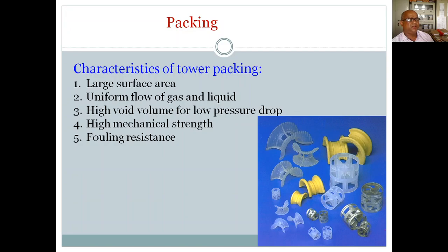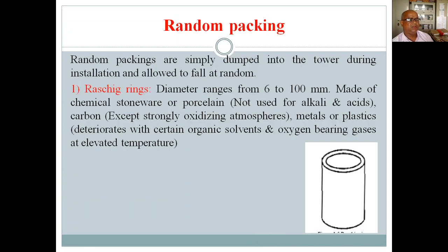So the characteristics of packing tower packing: larger surface area, and uniform flow of gas and liquid should be there. And high void volume, so that there will be low pressure drop, high mechanical strength and fouling resistance. So these are the best characteristics of the packing material. Now we will see the first packing, that is the Raschig